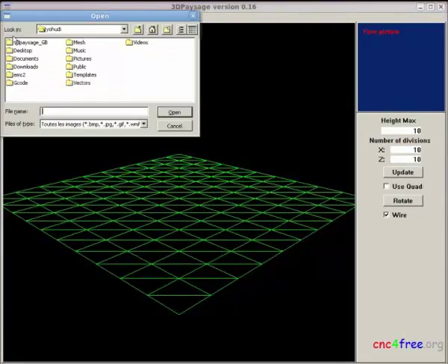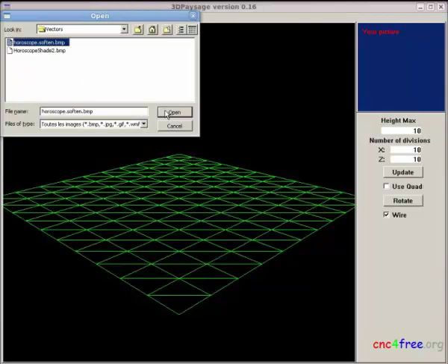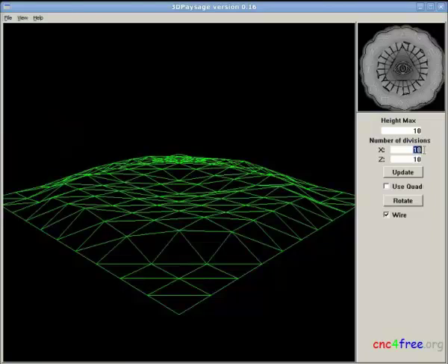File, Open Picture allows selection of the required height map. When the height map loads, number of divisions value is entered. For triangle-based meshes, a 1-to-1 pixel-to-face ratio produces the best results. Each square mesh division comprises 2 triangular faces. Division setting of 540 by 540 creates 1080 faces along each edge.